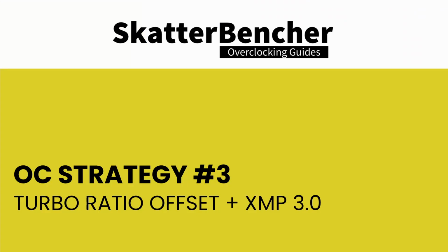In our third overclocking strategy, we make use of MSI's unique turbo ratio offset feature. Turbo ratio offset allows us to increase the turbo ratios over the default configuration by a certain amount of bins. This is very helpful as it allows you to set a dynamic overclock without having to dig too deep in the BIOS settings.